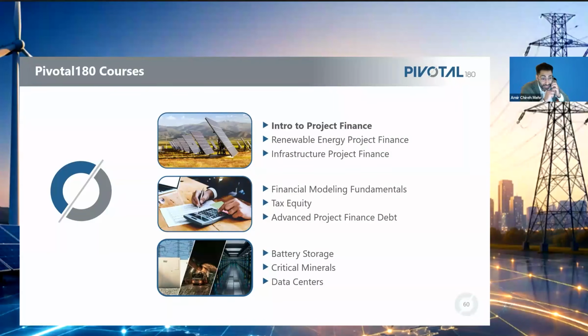Battery storage can do that in some cases. Some natural gas-fired assets can. Large hydro pump storage assets can, open the sluice gates and let water tumble down the dam and provide near instantaneous electricity. But obviously, other asset classes, nuclear, wind, and solar, geothermal are going to be much more limited in their ability to dispatch. So it depends, right? And even within an asset class, like a natural gas-fired power plant can typically be turned on pretty quickly, even if it's a combined cycle plant. You don't really want to go through the wear and tear and the damage of turning something on for an hour, because you might need to then let it cool off for half an hour as the case may be.